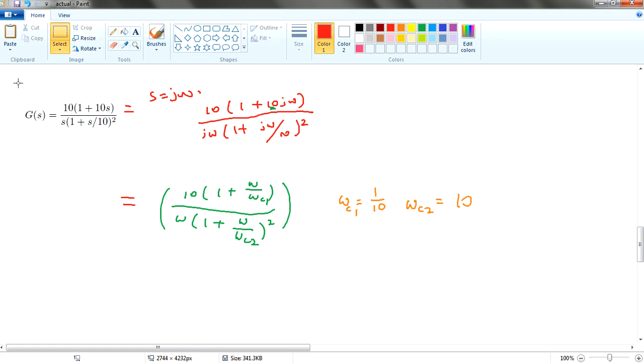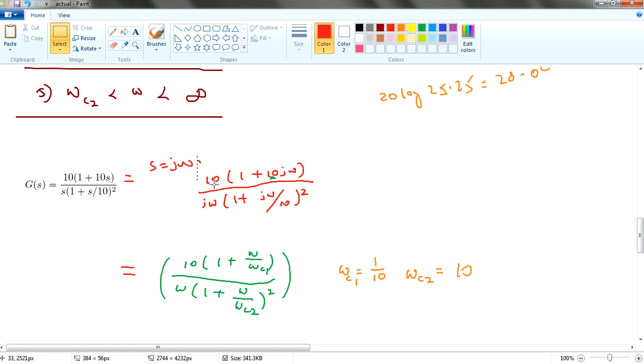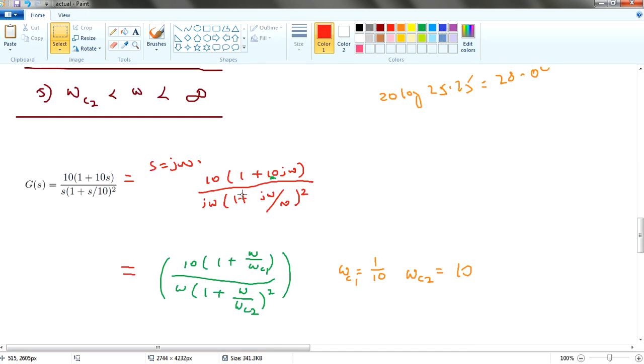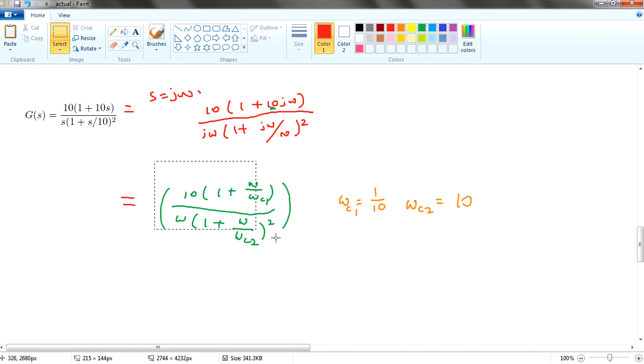So now there's the phase Bode plot. Similarly, like your gain Bode plot, the first thing first, you change your s equals to j omega. So this should come in the same step as your gain margin. Okay, your gain Bode plot. So if you were to redo everything, you have this formula over here.